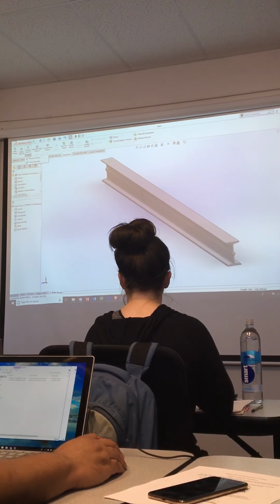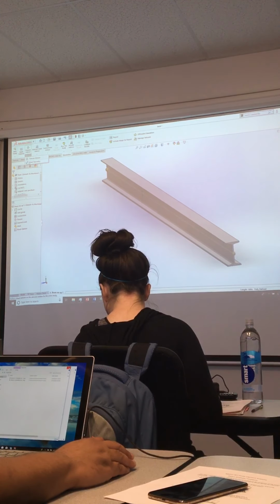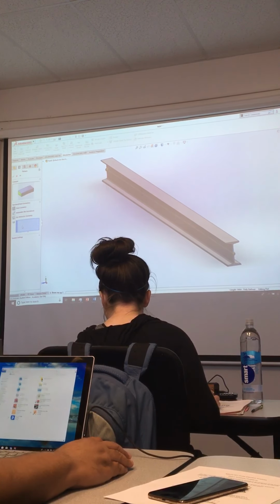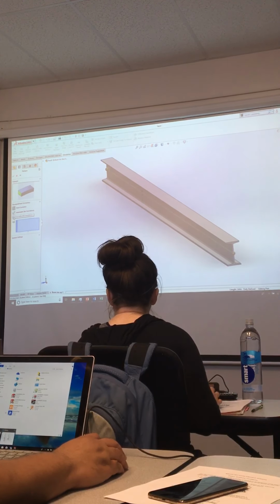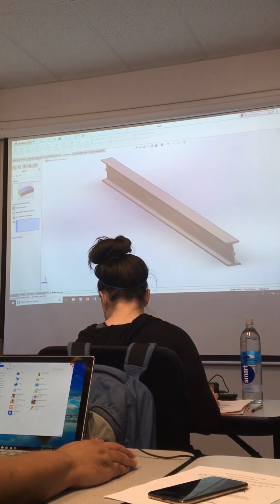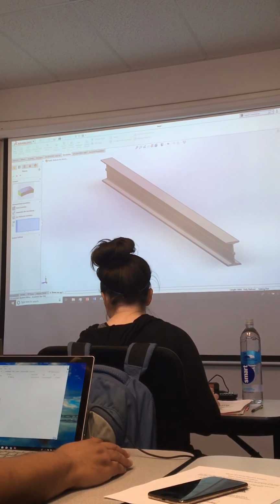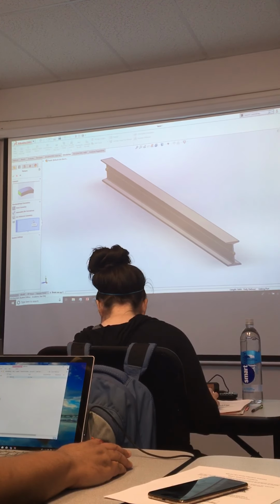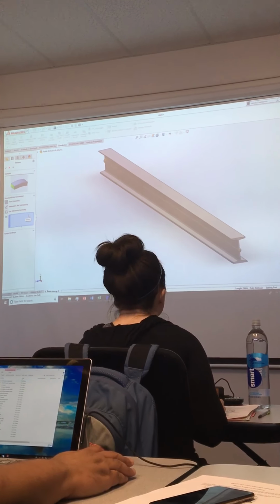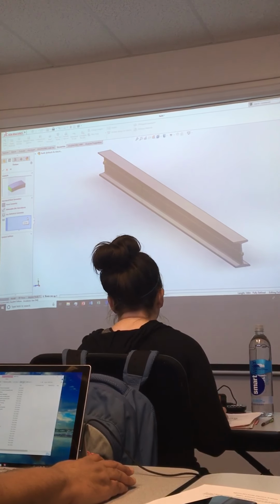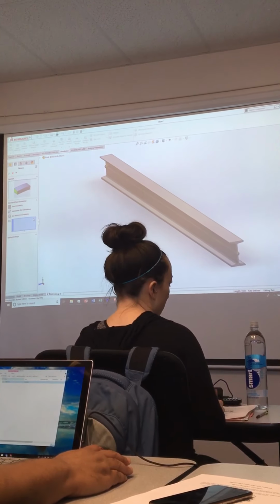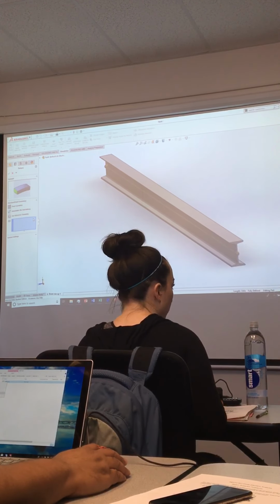So let's go apply displacement constraints. We got very little choices here, we got fixed geometry, so okay. I don't really want fixed geometry, but immovable is not a bad choice. And you notice the only thing I can pick on here is this little symbol over here, which tells me the only thing I can apply my displacement constraints to is the joints. I can't apply them anywhere else. So if I want to apply them in some particular place, I have to make a joint there. Okay, to be able to do that.